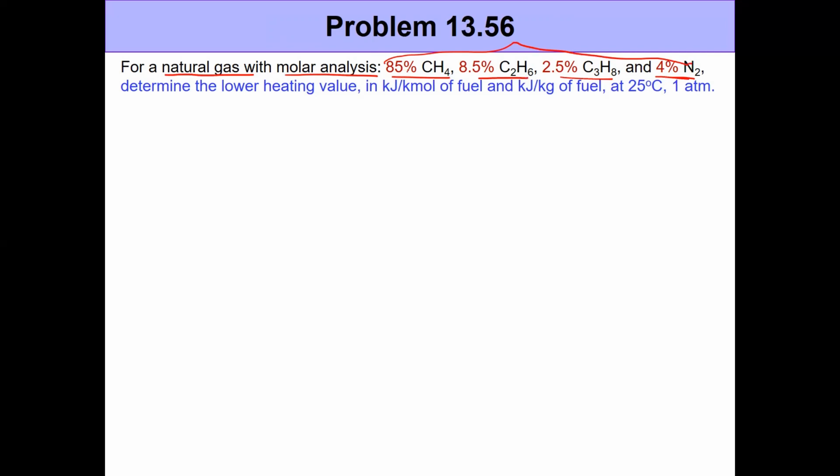We don't have a single-component fuel; we have a mixture of fuel. And the question is, how do we evaluate the heating value for this? Here, we just need to determine the lower heating value in kilojoules per kilomole of fuel, as well as kilojoules per kilogram of fuel at, again, the same condition, 25 degrees Celsius, 1 atmosphere pressure. So this is what we're trying to do here.